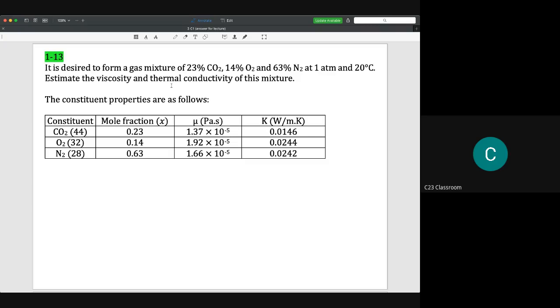For liquid, it is not worth it for us to do the estimation like this, because if you mix, for example, oil with another oil plus another nanoparticle and so on, the best way to know the viscosity is to measure it by the viscometer, because the liquid can be of many kinds. Can you get me?